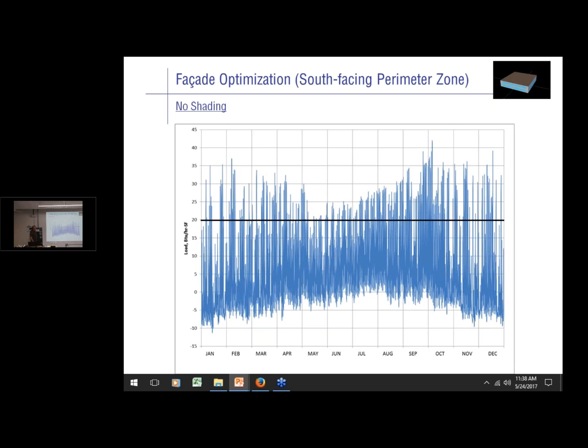You can clearly see the south zone. Anyone surprised that our peak is happening here and not here? Sun angle and reflection off the glass. This is a solar-driven load dynamic, and in the high sun angle months, we have less transmitted solar load through that window, even in an unshaded condition, than we do in the lower sun angle, but still warm afternoons. This is a pretty classic Pacific Northwest south zone load profile out of the box.